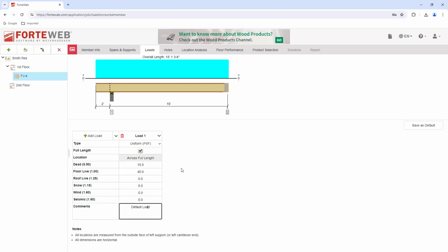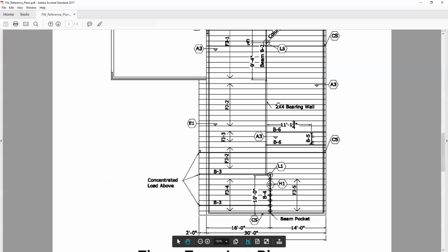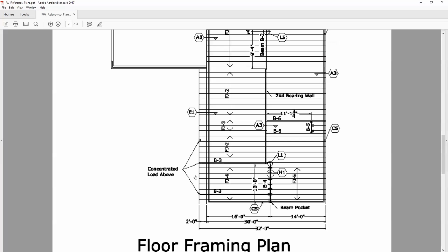Now I want to add another load, and I'm going to explain the loading to you as I bring these over to you. So right here, we have our default load coming across. That's just our typical 16-inch on center, our 40 and 15 loading. Then out here on this cantilever, we have a point load, and that's going to be in pounds per linear foot of our wall above this. So if we were framing this house, there's going to be a wall above this.